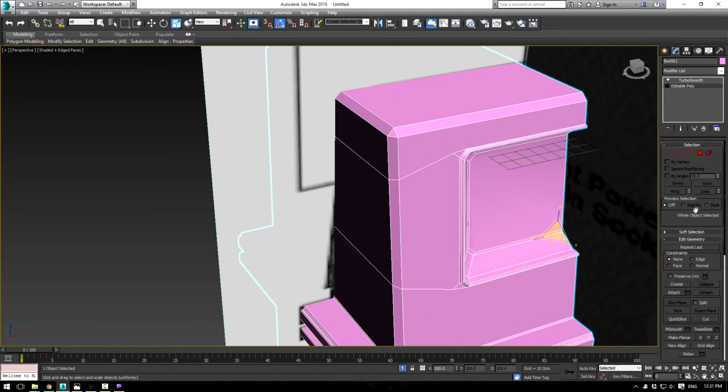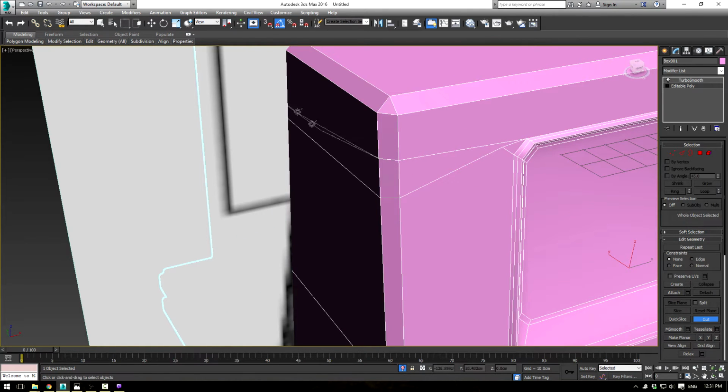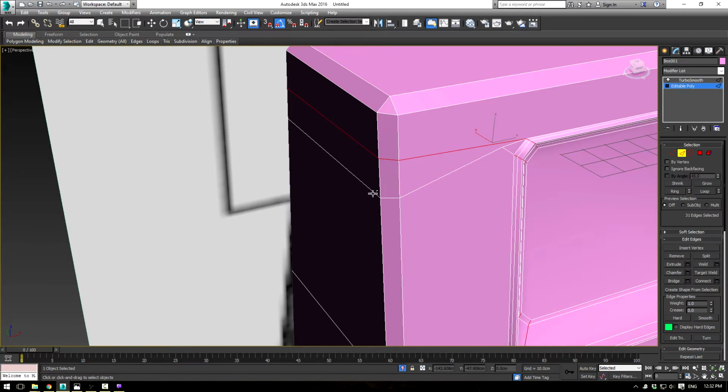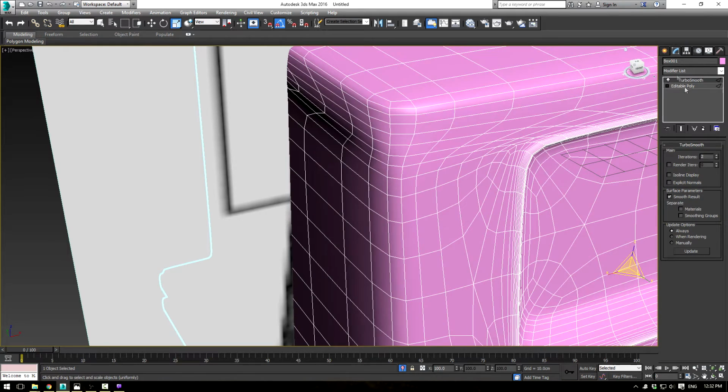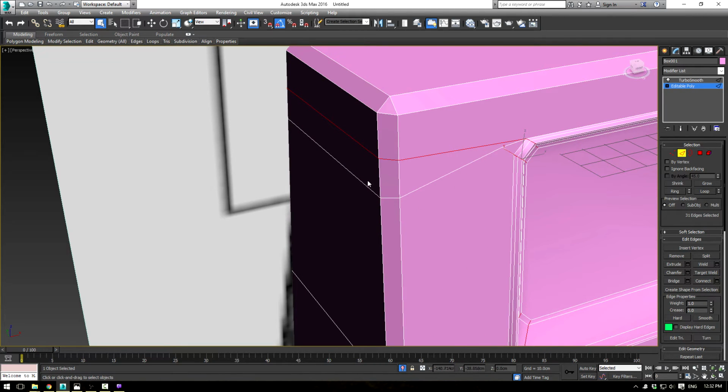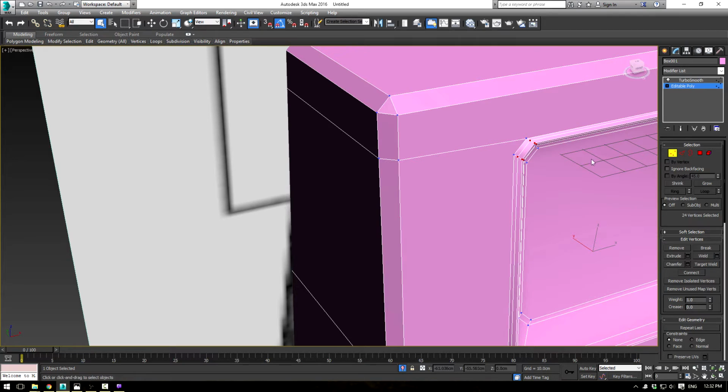I think we can fix it, so let's go ahead and we're going to cut from this point sort of over, and out, and then we can go ahead here and getting out of your cut selection here, press Q. Just press Control Backspace on all of these lines here. Alright, and now you'll see we have sort of a little bit better mesh there.